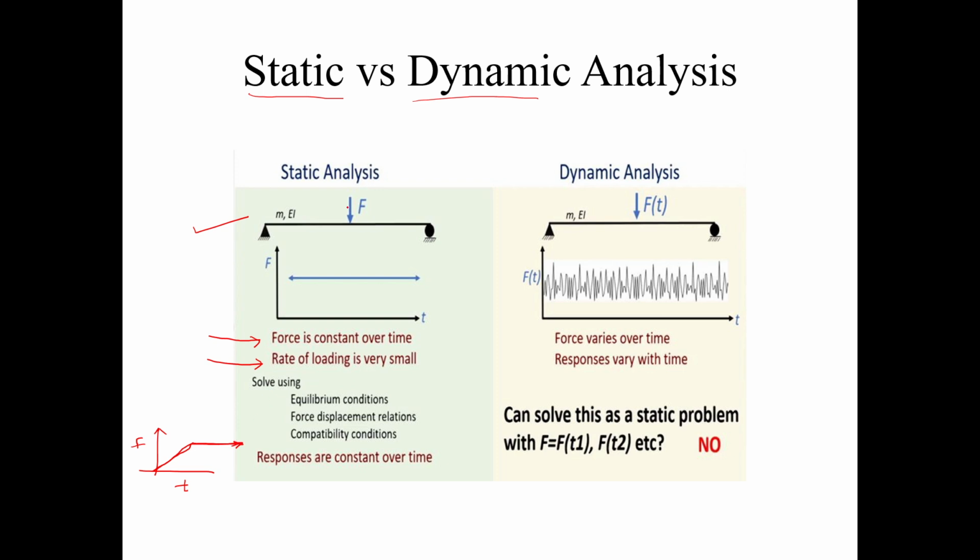Such problems can be solved using equilibrium conditions like summation Fx equals 0, summation Fy equals 0, and moment at any point equals 0. Or you can use the force-displacement relationship, or the compatibility condition. One thing to notice: as the force is constant over time, the response is also constant.